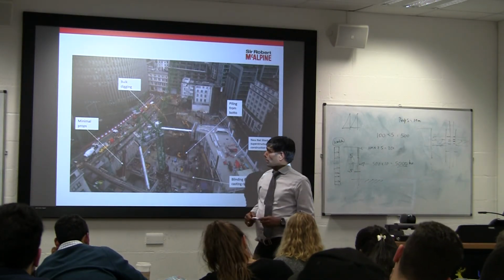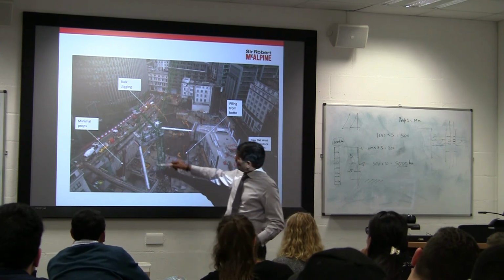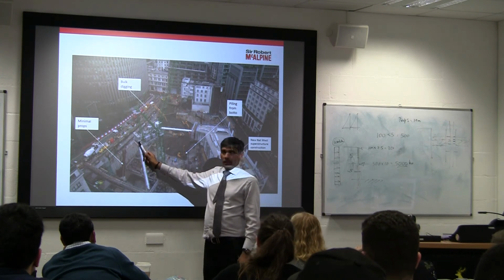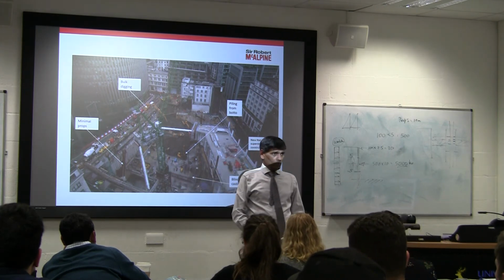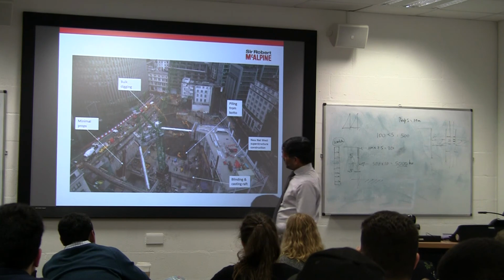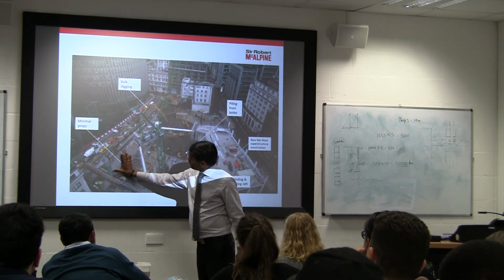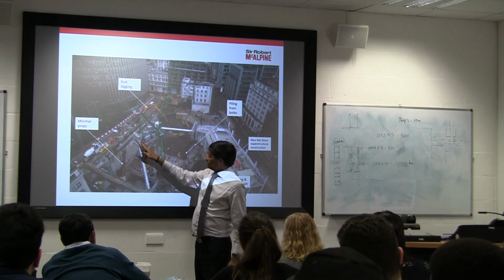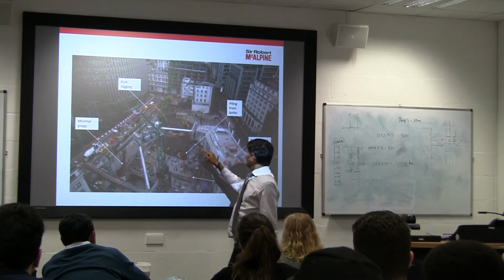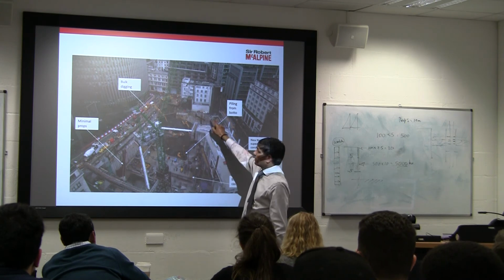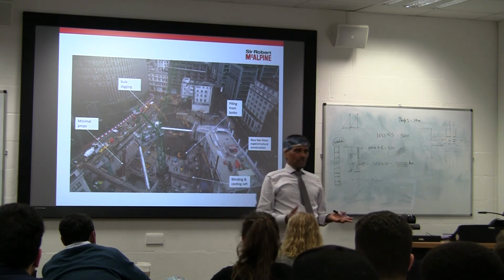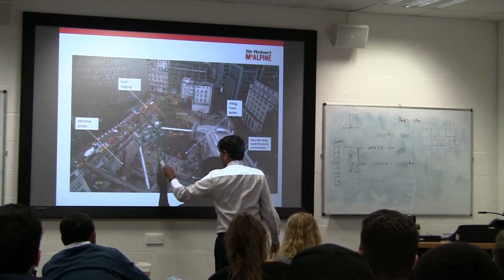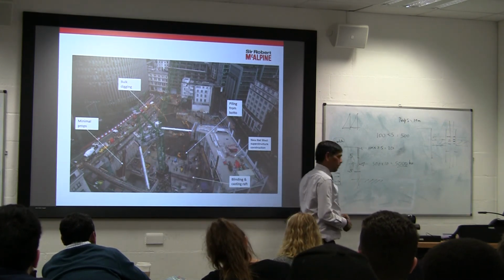So this is where you can see the prop is kept only at one level, at the capping beam level, and then we are digging right down to the bottom. This one prop, spacing of these props will be about that spacing. You can see it's equally divided. That is 50 meters, roughly about 10 or 15 meters. So there's a prop there, there's a prop there, there's another prop there, there's another prop in those corners. Yeah? So you know the spacing of the props, you know the load, and you manage the forces on those props only.